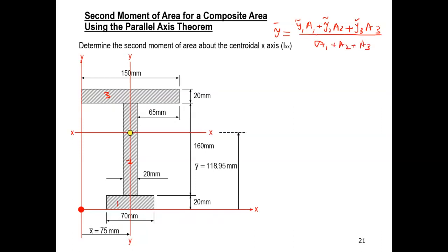So the question is, I do need to take a reference. So this x is my datum. So when I find y bar, it would be calculated with respect to that datum. I could have taken the datum at the top or at any place, but now I take that from below. When I calculate, I note that this is my reference.